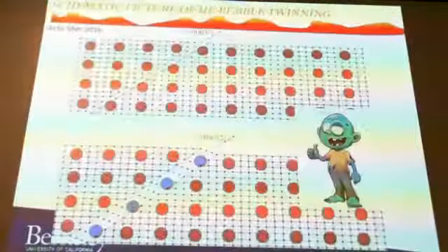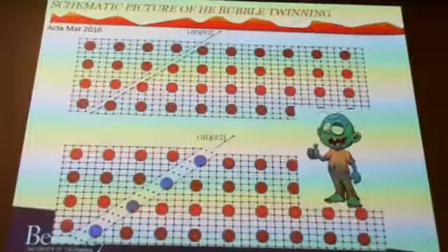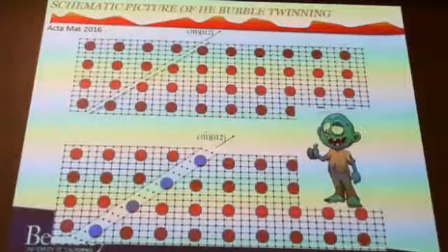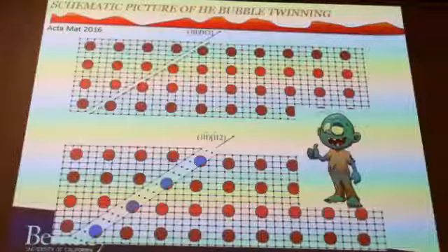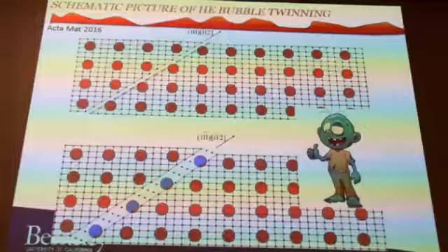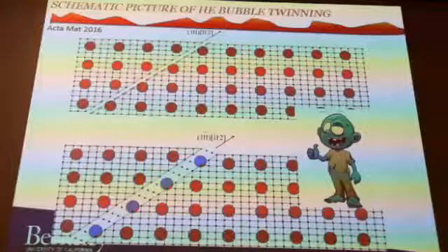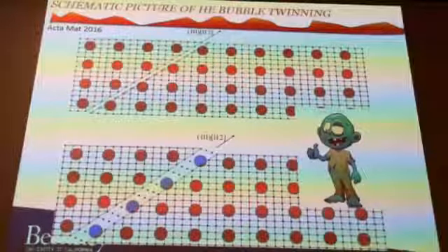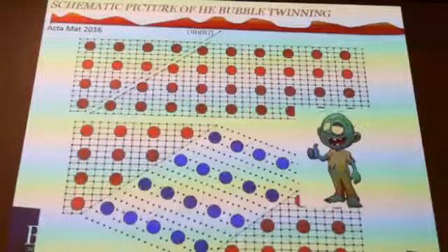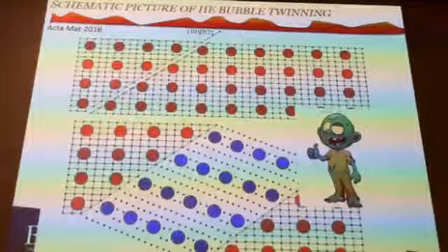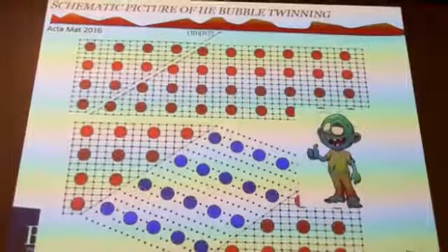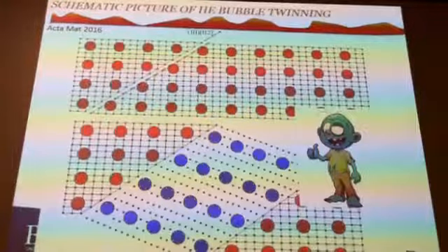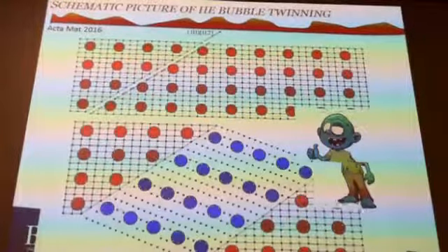The way this may happen is if you have your lattice and you have your helium bubbles here, and you pass partial dislocations through, and you assume these dislocations cut through the helium bubbles, then you would assume each helium bubble is getting moved by half a Burgers vector due to that cutting process, which eventually leads to the rotated lattice, but also to the rotated helium bubbles. So this is sort of fundamental, but kind of fun to do because you can flip things over, basically, or cut them in half.